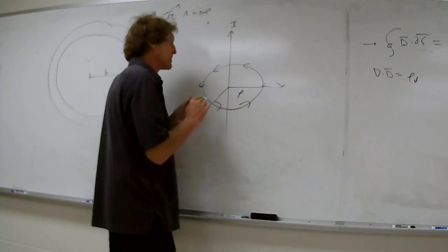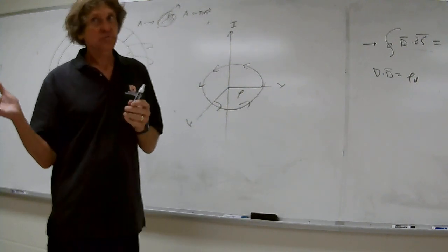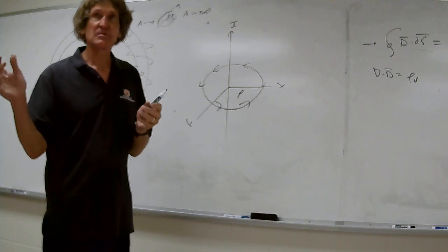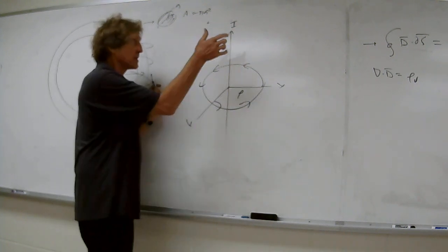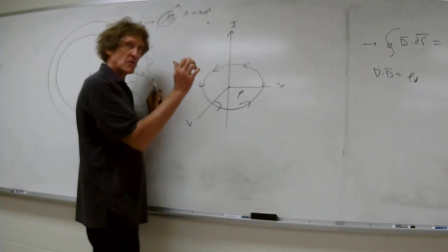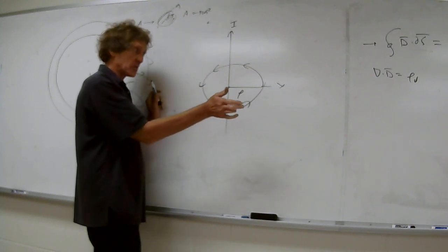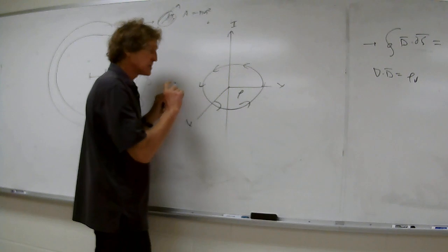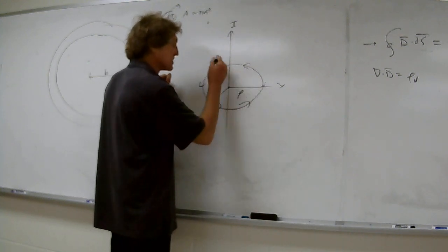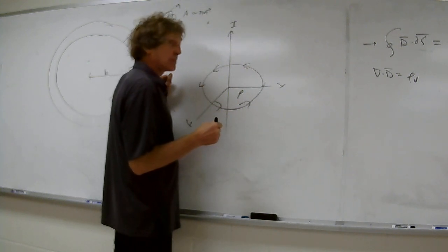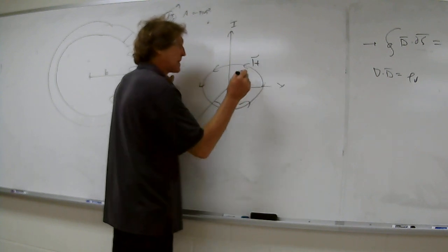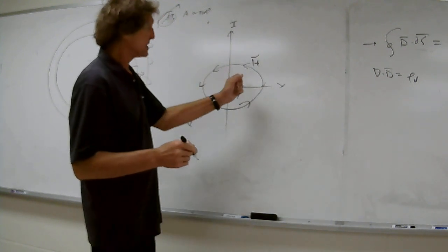And I take a look at this. If this is an infinite current, this is where you have to have some common sense, really an understanding of the phenomenon. Remember I told you if you use your right hand and put your thumb in the direction of the current, your fingers curl in the direction of the H field. Do y'all remember that? For each one of these points, you're going to get an H field that will be symmetric, and it will be in the azimuthal direction. So if I apply that law to this event,